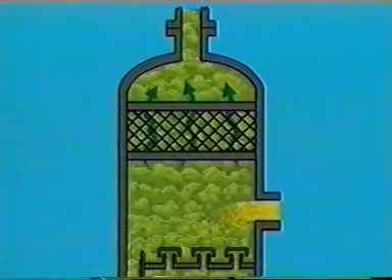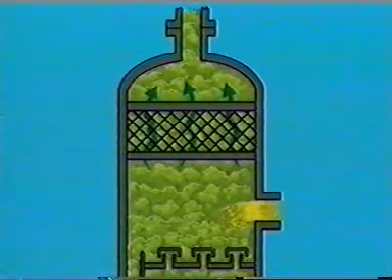Carryover occurs when glycol contamination causes foam buildup. Carryover also happens when the gas rate is high enough to agitate the liquid on the top tray so that a foam forms that is too thick for the mist eliminator to handle. The gas rate must be reduced to eliminate carryover.